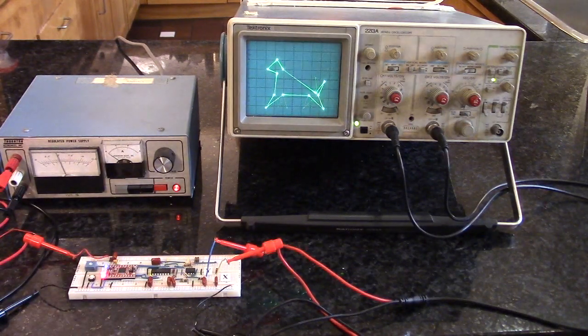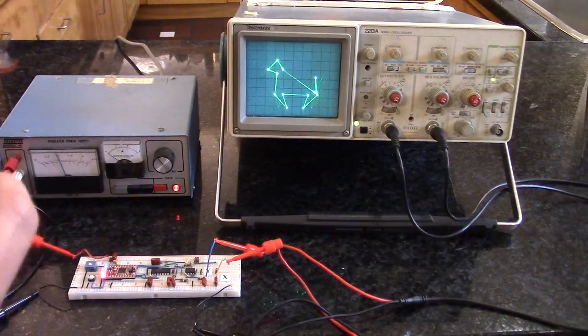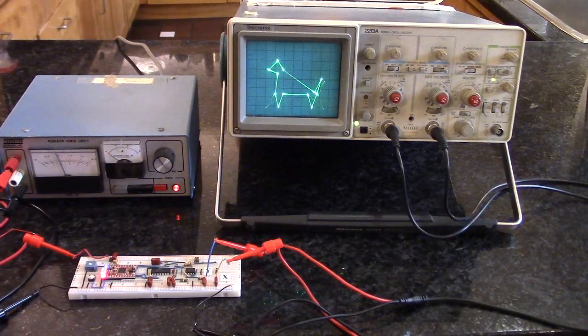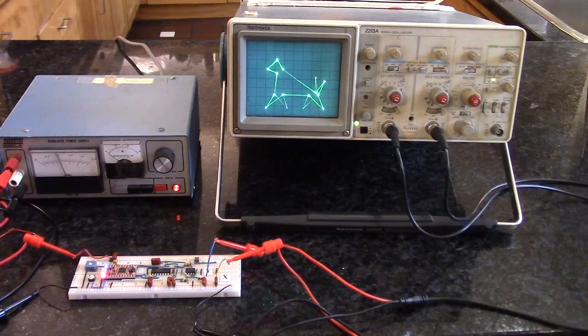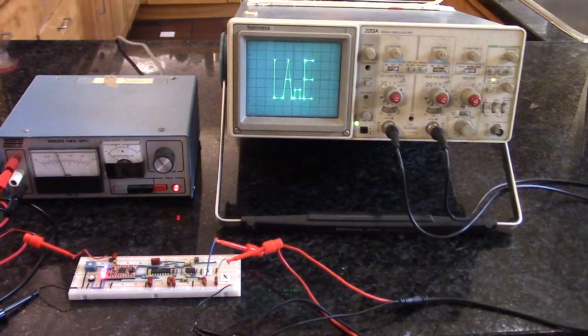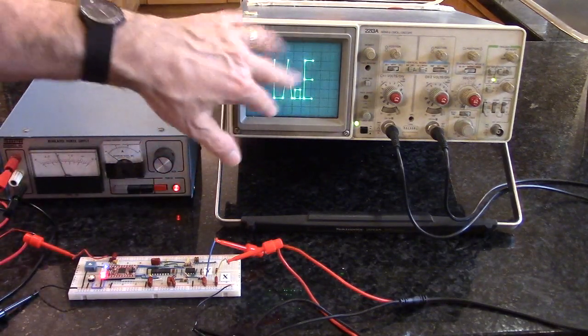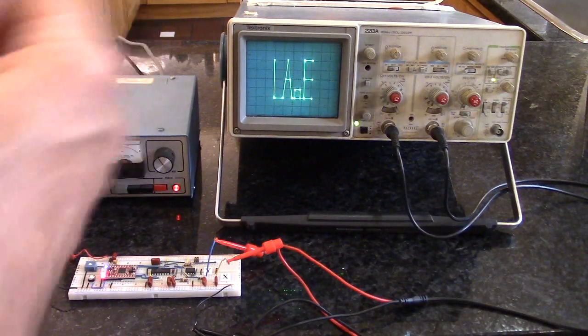And why don't we zoom in and look at some of these again. Now, one thing I should mention is that we've put an RC network on the output of the DAC. If we didn't do that, we would move very quickly between the dots and you wouldn't see the lines between them. We've got 2.2K times 0.01 microfarads. Let's see what that is. And that's 22 microseconds. And what that does is it slows down the output so that you actually see the beam as it traverses. If we didn't have that, it would look like just a series of dots.